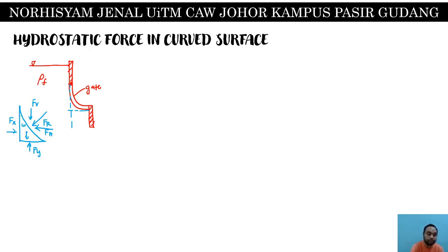Okay, so if this volume is here, there will be a change in two parts. The first part, the change that we will have is in terms of summation of Fy equals to 0. Fy is sensitive towards the shape of the volume. For example, right now, if you can see, the Fy over here is at the bottom part of the curve. Okay, so if you do Fy, and W will be different compared to the one that we did before. So based on this volume, you can see that the Fy is acting upward for this question, and minus W minus Fv equals to 0. So Fv is equal to Fy minus W, and this is different compared to the picture that we have before, because the picture that we have before this is Fy plus W.